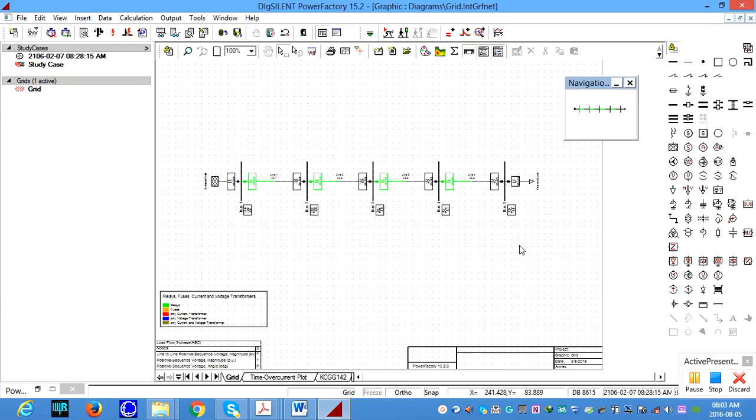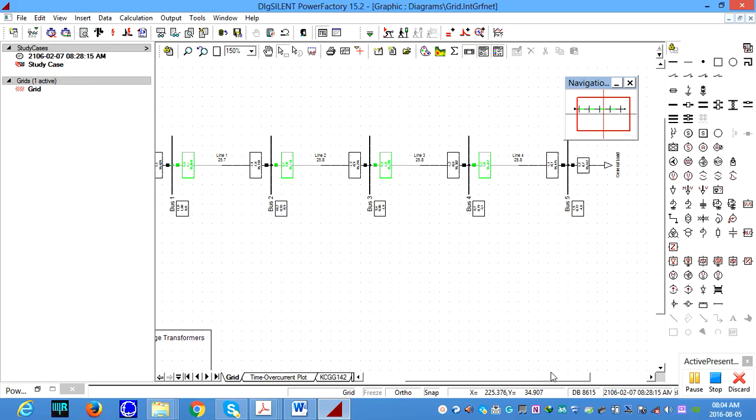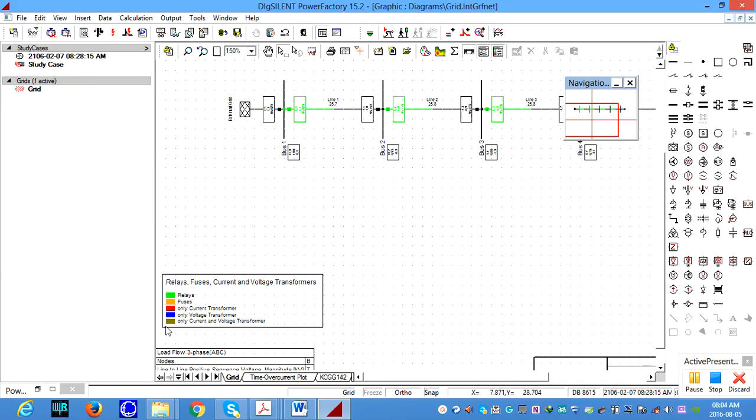Then once you model it, you need to conduct the load flow successfully. I assume from the first video clip you know how to model the network and conduct the load flow. Once that is done, next we need to include the overcurrent relays on buses 1 to 4. In this picture from the video clip you can see the relays.